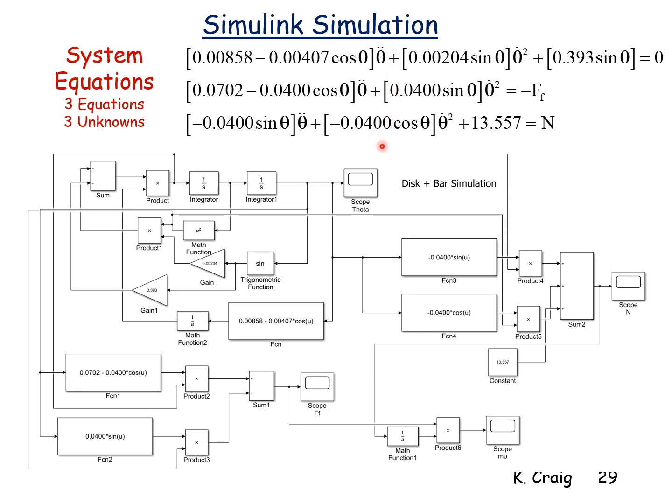So I have three equations, and I want to now generate a simulation diagram for these three equations. I have my two integrators. This line represents theta double dot integrated once with an initial condition on angular velocity, which is 0, will give me theta dot. Integrated again with an initial condition on angular position specified in radians, nominally for small oscillations less than 15 degrees, but we express it in radians, will give me theta.